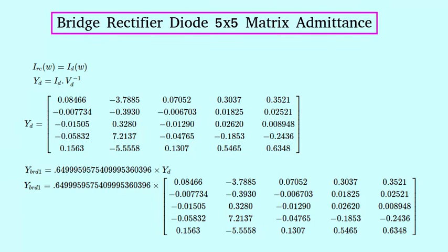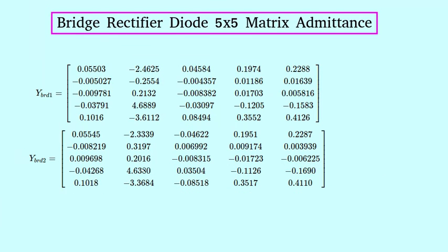We'll insert these 2 matrices into a SPICE type of program to calculate the load voltage. So then, using a lot of trial and error, we'll find the constant, which can be used to make the diode matrices give the same output DC voltage as the simulation gives for a bridge rectifier circuit, and this is it. And after multiplying these 2 matrices by this constant, we'll obtain these 2 bridge rectifier diode matrix models ready to insert into a circuit simulator program so as to solve for a bridge rectifier circuit.